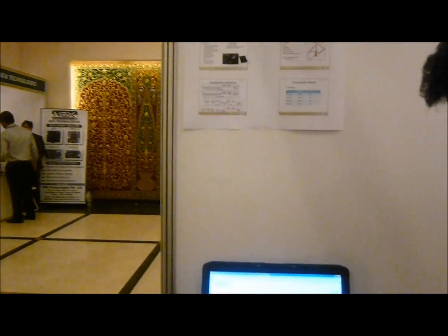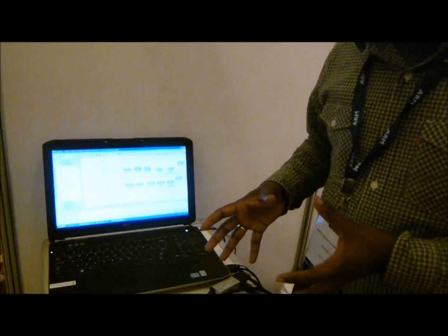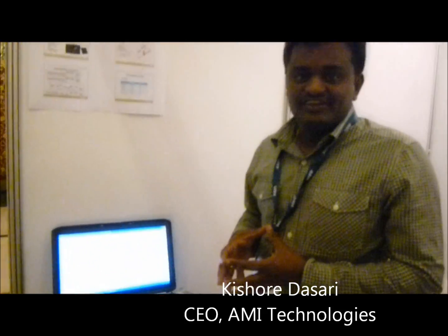This demo represents the next generation automotive infotainment system. In current high-end cars, we have the infotainment system, the navigation inside, the controls for the AC, and then audio processing running in the background. Generally we use a separate processor for the navigation and touch panels, and then we use a DSP in the background for all the audio processing. But because of the Cortex-A9 with its powerful NEON instruction set, we would like to achieve both things in a single chip, on a single SoC.